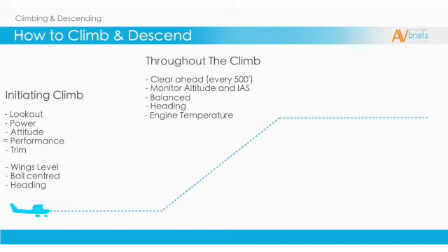The way to reduce an overheating engine is to simply lower the nose attitude slightly. This will increase the speed and get more air flowing through the engine. If that doesn't work well enough, you can also look at reducing the power. You would obviously need to lower the nose attitude more, to maintain your desired airspeed.